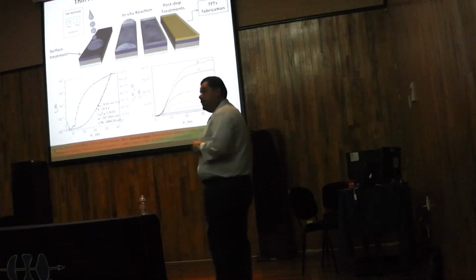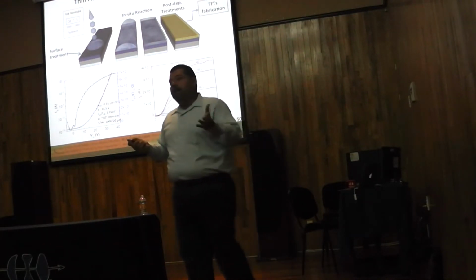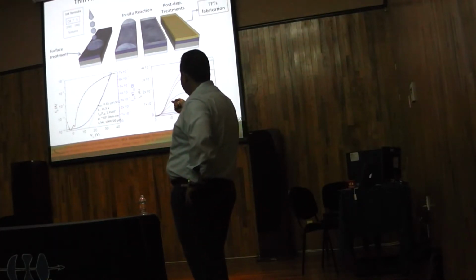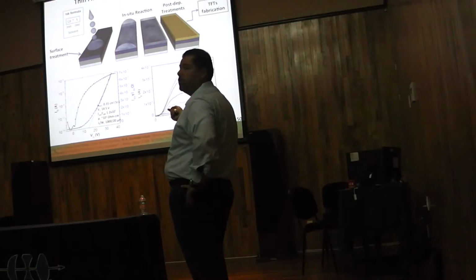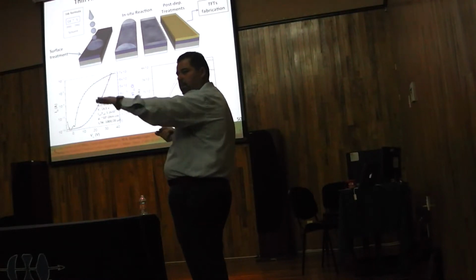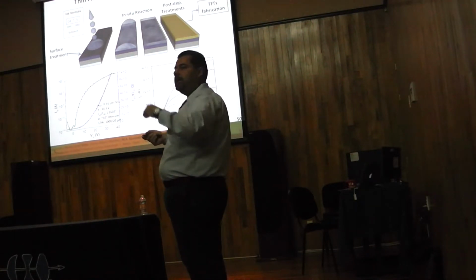We also do inkjet process. Remember we're talking about large area. So we have what is called micro or micro drop casting. We have an ink that has the cadmium and the sulfur. The advantage of this is that I only use the material where I need it. In photolithography, you need to cover the entire substrate and then you remove selected areas.